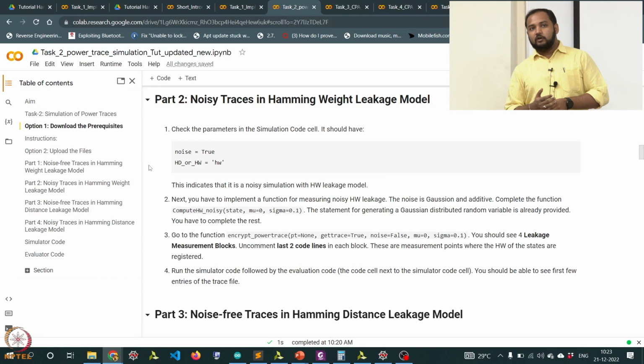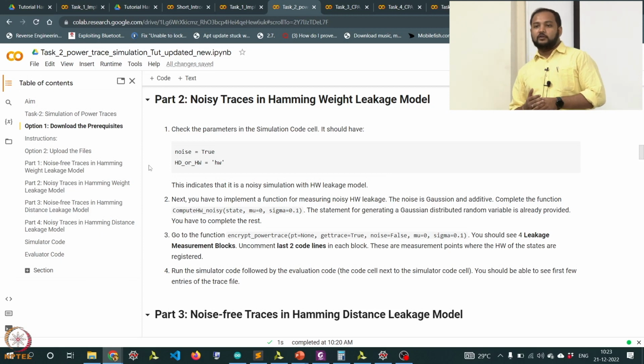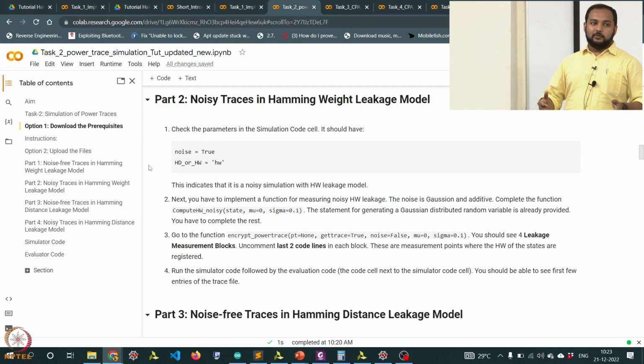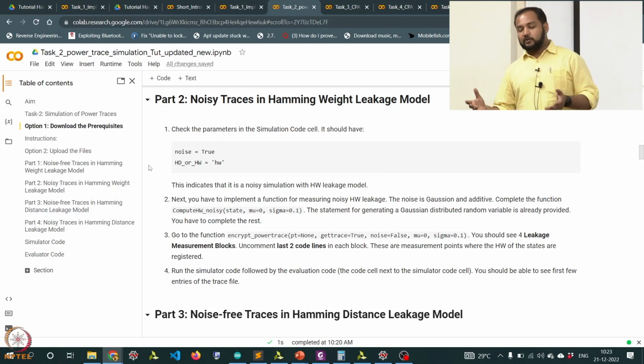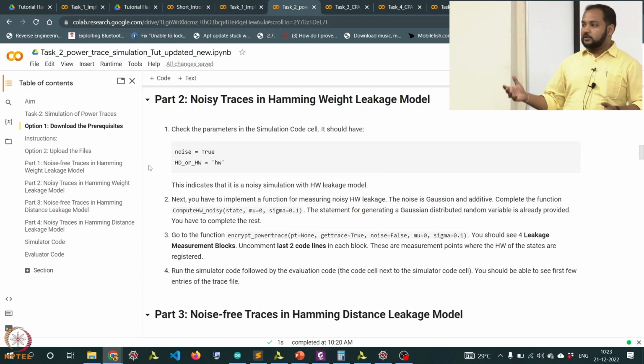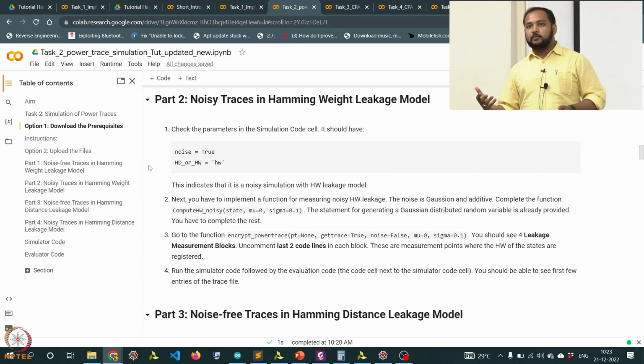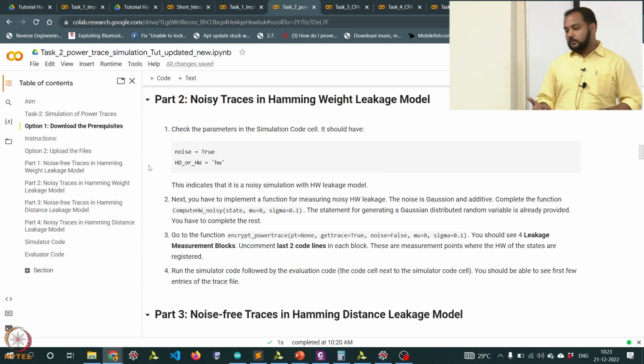Ideally, collecting traces takes a whole day. We have to collect around 25,000 traces, that is 25,000 runs of the AES on an FPGA, so it takes a whole day. Based on that, in order to perform CPA in a real-life experiment, we see that we need around 4,000 traces if your probe is good. If your probe is noisy, you need around 10,000 traces in order to perform a successful CPA.